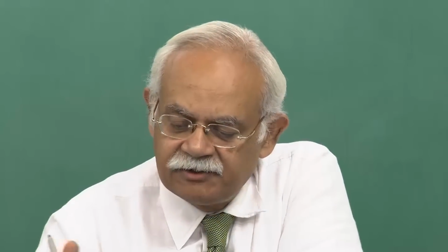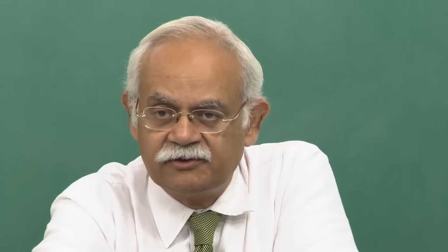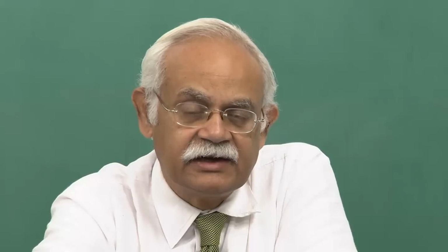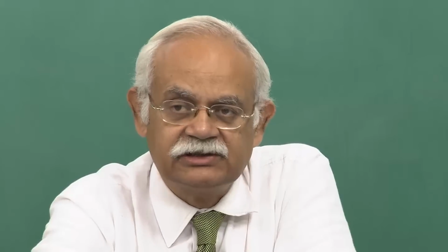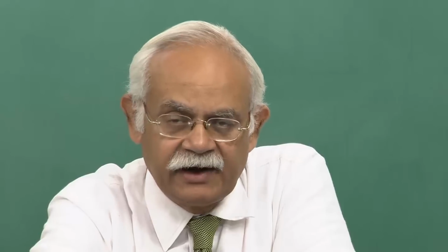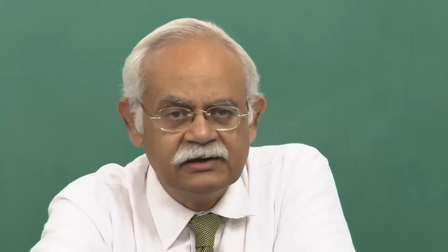We do not see much difference between the secant modulus and the chord modulus, and of course the tangent modulus will keep changing. So it is not a matter of which of them is true or false. It is only a matter of how we define it, and also keep in mind the range of stress in which most structures operate. There we find that most structures actually operate at levels lower than 30 to 40% of the ultimate stresses for most of the time, and that is the basis for using this 40% to define the point S on this stress strain curve and moving forward.